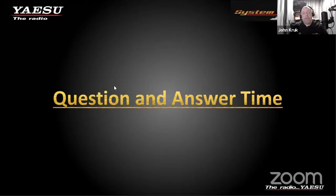So what tends to happen is that we get a lot of these calls in technical support. Fusion is horrible. It's no good. Well, we'll ask, how are you using it? And they say, well, I'm using it with the hotspot, or in this scenario. Right away, we can tell that there's a bad bit error rate. And we'll say, hey, can you use it on a Fusion repeater? Oh yeah, the Fusion repeater works great. Can you use it on a Wires X node? Oh yeah, the Wires X node works great. But when I'm using it with this device, it cuts out, the audio is horrible and everything. Well, that's usually related to bad bit error rate.